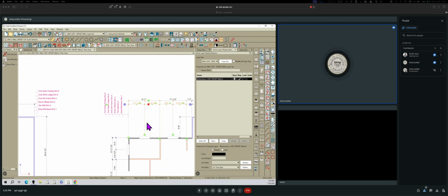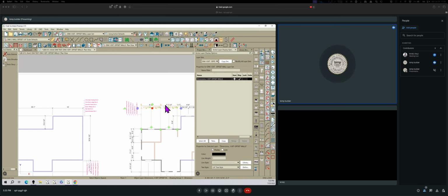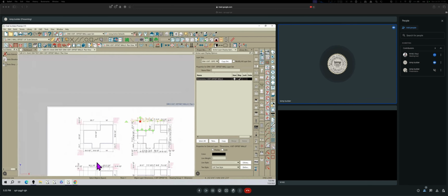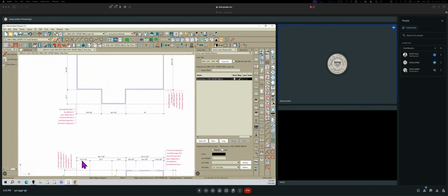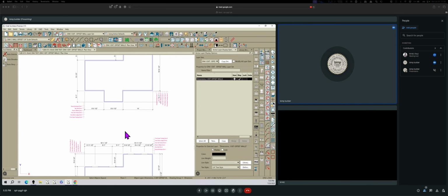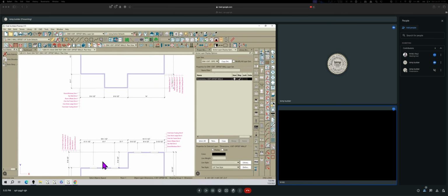It's cleaner dimensions. If I had to lay out that plate, that overall dimension there, see, it's cleaner. If I had to lay out those plates, the one on the upper right, I would have to lay it out, and then I'd have to readjust my tape over the layout for the T-wall to get to the next window. And I would not want to do that because that introduces the chance of me getting off, instead of staying hooked. You hook that tape right there, and you come right across here and get the center line.